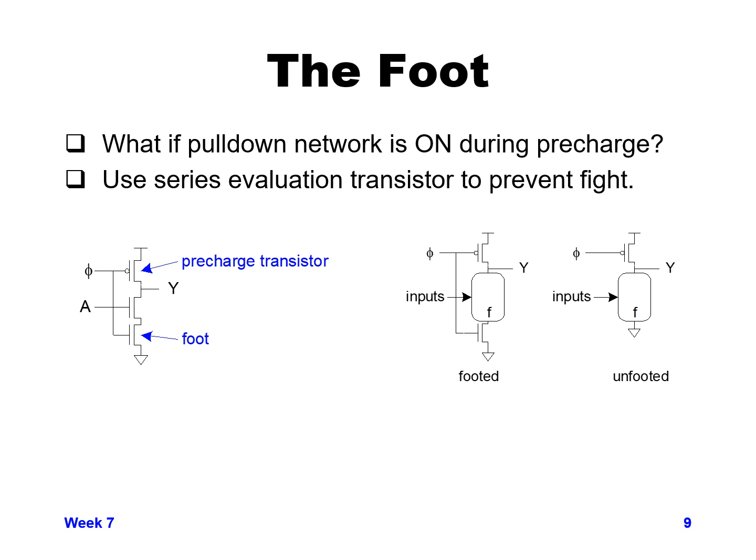So here's where the concept of a foot comes in, and having a pull-down network that has a foot in it. The foot is a single NMOS device that is connected to ground, and all of our other inputs, our normal inputs, not the clock input, need to be in series with this foot device.